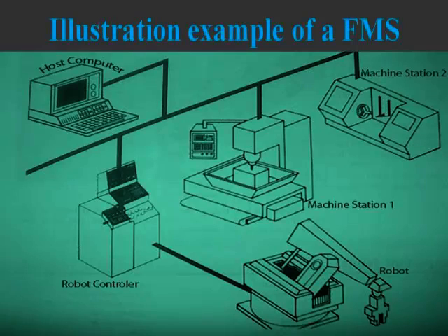Parts can skip stations for flexibility, used for large part sizes, best for long process times. This is inline FMS layout, where the loading is at one end and completion of the parts at the other end. Work parts are flowing from one end to the other end and getting processed on the various CNC machines or automatic machine. This is inline.